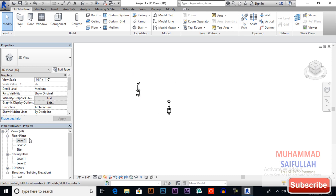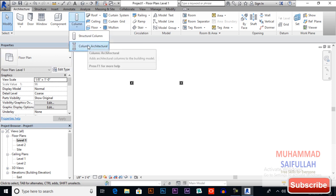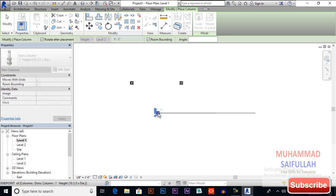Now switch back to level 1, and switch back to column architecture, and here we have the option rotate after placement. So I checked it, and now when you place it somewhere in your drawing, after that you can rotate it, and you can specify its rotation angle. For example, I will do a 45.